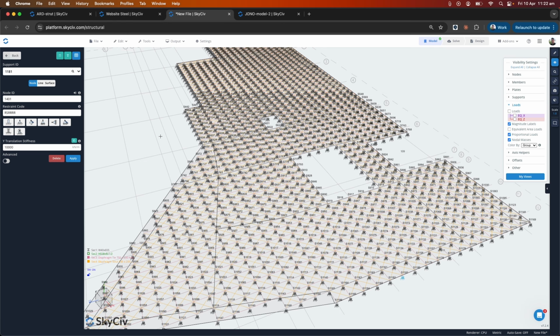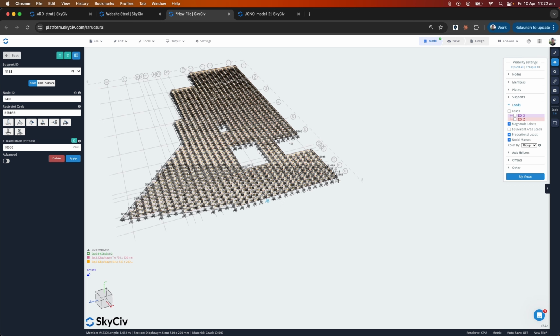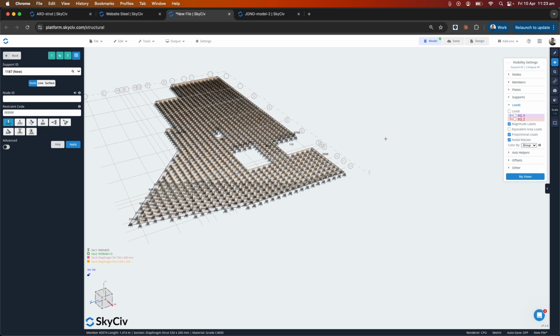And yeah, you might want to introduce some supports in the X and the Z direction, obviously because we've got loads in that direction, but we have no restraints in those. So just for the purpose of making the analysis work, I'll just put in a fix in the X and the Z for that node, and maybe a node out here. Do the same. Obviously, you can fully control where you're applying those restraints, those lateral restraints, but I'll just do that for example's sake.